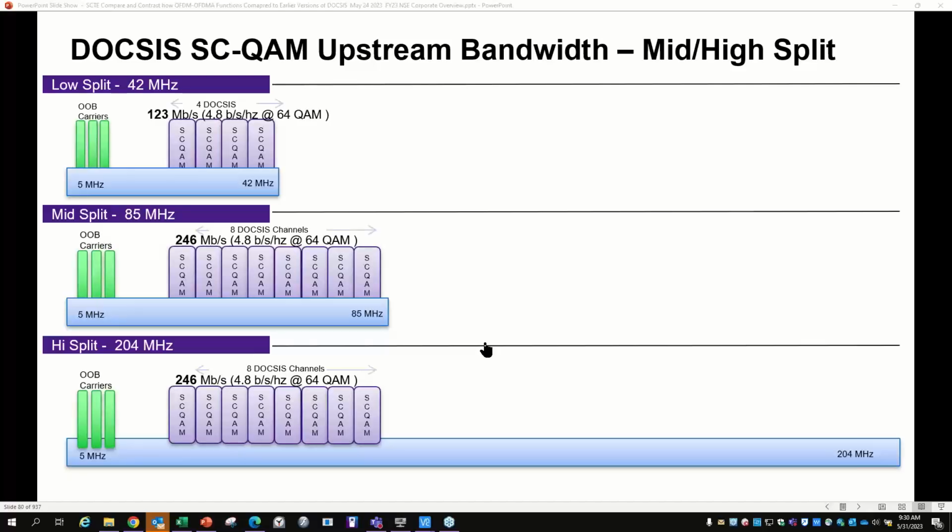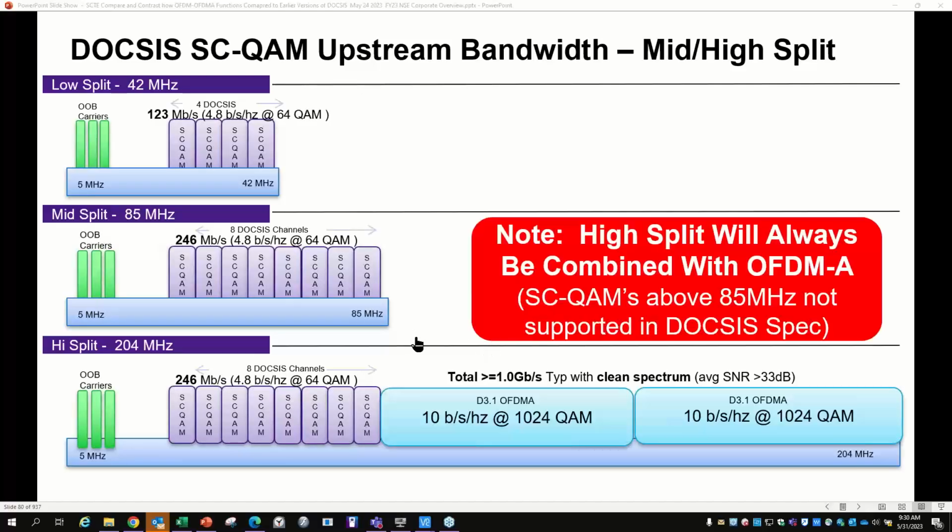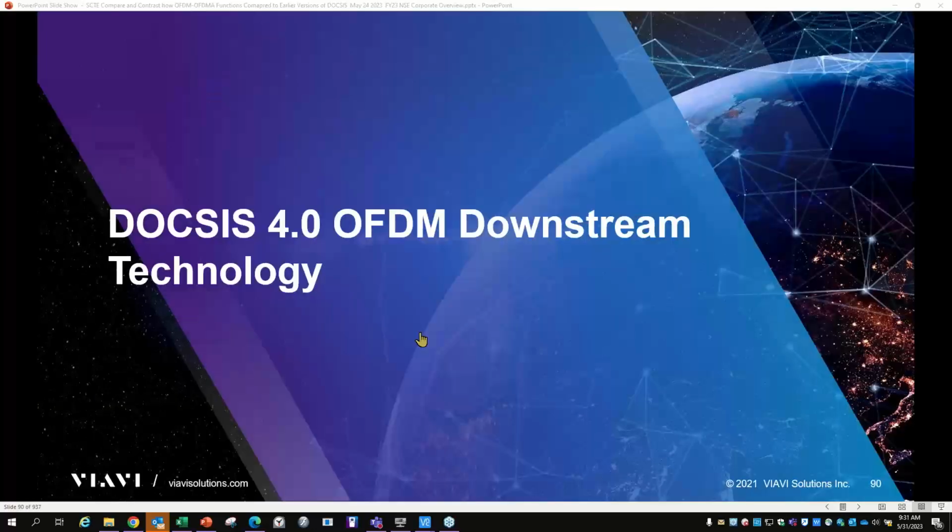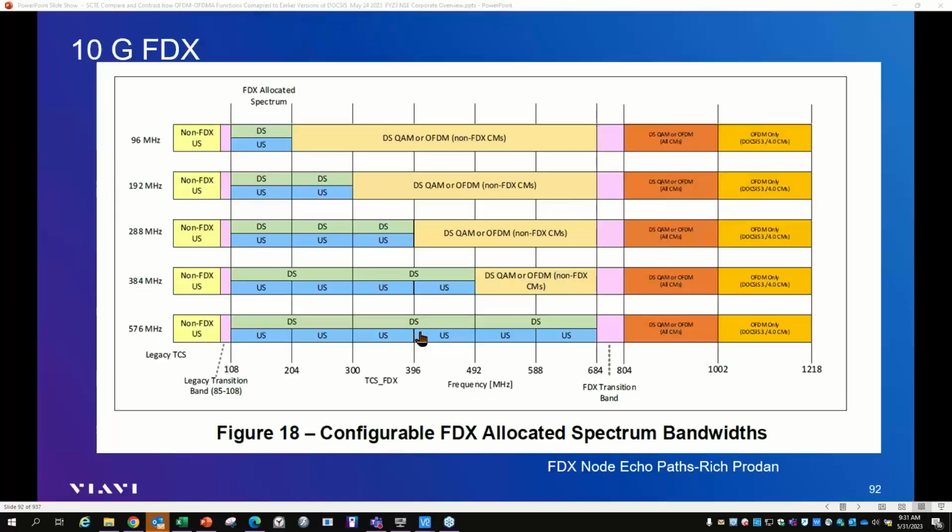Well, as we look at these scenarios and the deployment of these single QAM carriers and OFDM carriers, right? The next evolution has already been spoken of for several years, and the next one is really DOCSIS 4.0, for example, and the ability to deploy FDX, full duplex, right? So they want to be able to expand instead of 204, go all the way to eventually 300, 400, 500, and 680 megahertz on the upstream.